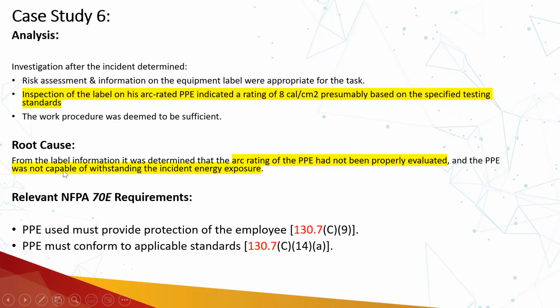So what was the root cause? From the label information, it was determined that the arc rating of the PPE had not been properly evaluated, and the PPE was not capable of withstanding the incident energy exposure.